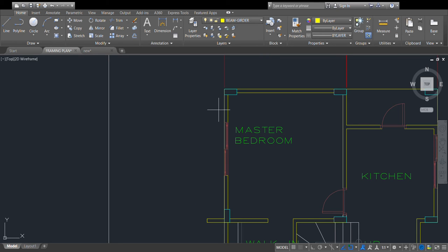So, press O for offset. I'll say 600 for the first one. And then, O again, this time 400. Remember, let me remind you that this scale is intended for 1:40, so be careful with other scales.